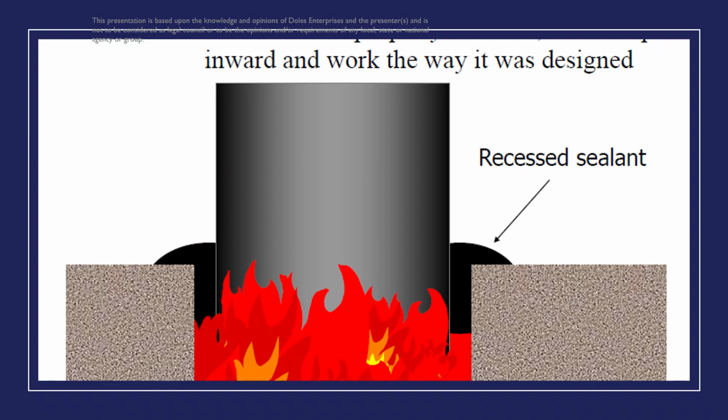Shown is proper application of a fire stop sealant or caulk. The annular space receives a certain amount of the caulk. There's also some tooling or sealant to the outside, allowing a bond to be created between the penetrating item and the substrate.